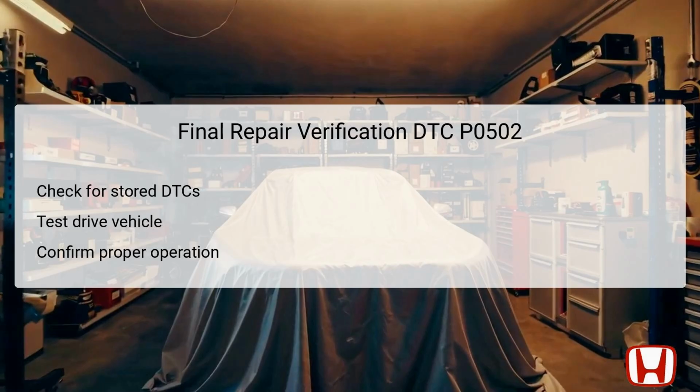To conclude the diagnostic process for DTC P0502, it is essential to conduct a thorough final repair verification. This begins by checking the vehicle's onboard diagnostics for any stored DTCs after repairs are made, ensuring that the P0502 code does not reappear. Subsequently, a test drive is necessary to validate the effectiveness of the repairs, allowing the technician to observe the vehicle's performance under real-world conditions.